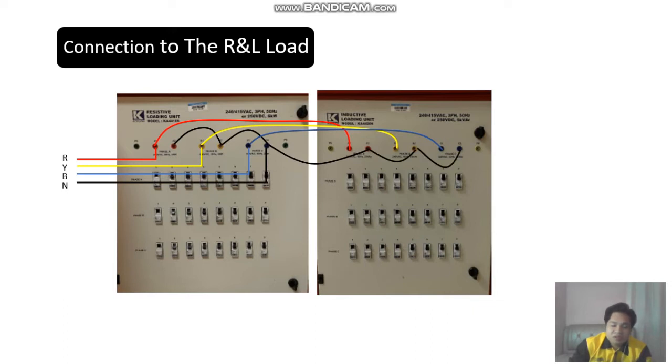After we've done our connection here, we can measure our power factor before we do our power factor correction. When we want to do our power factor correction, we need to add our capacitive load. So in the next slide, we'll be connecting our capacitive load.